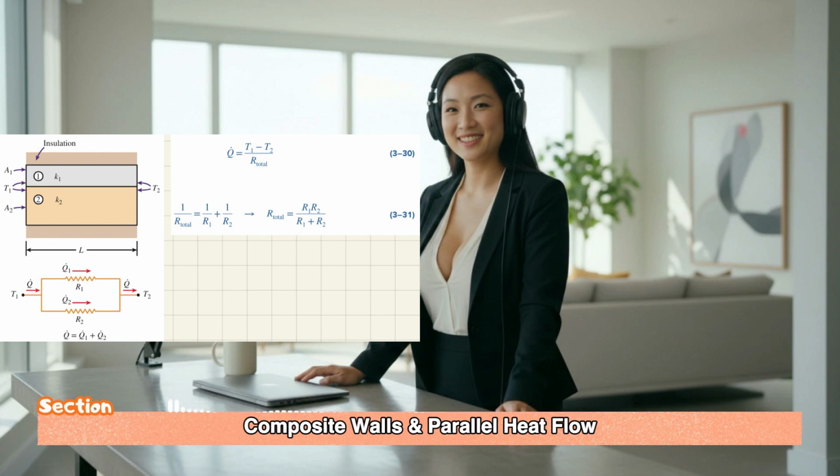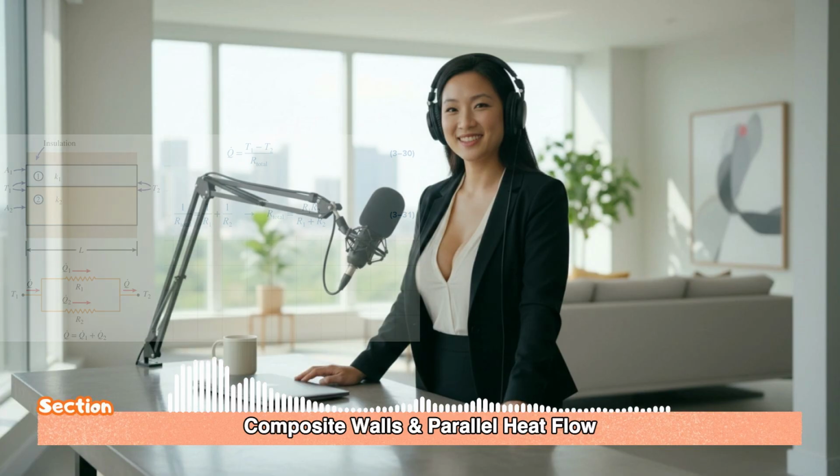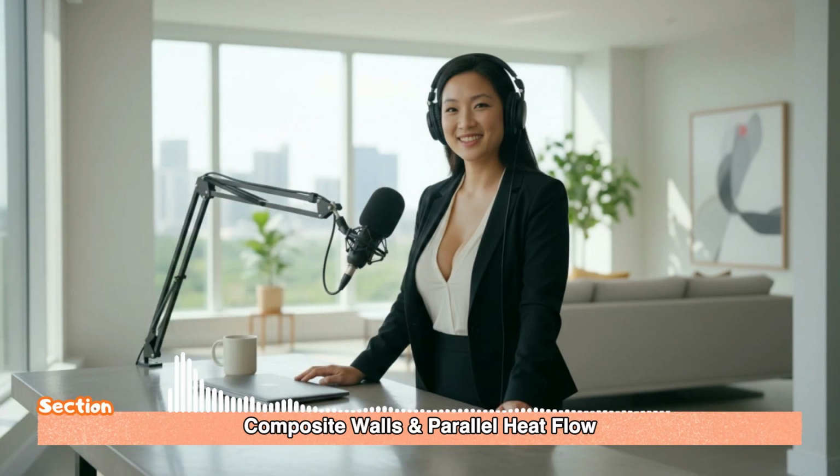It is. The total heat flow is the sum of the heat flow through the stud and the heat flow through the insulation. And because the driving temperature difference is the same for both, the equivalent resistance is calculated using that reciprocal rule: 1 over R total equals 1 over R1 plus 1 over R2. In a parallel system, heat always takes the path of least resistance. So if the wood stud has much lower resistance than the foam insulation, the vast majority of the heat will bypass the insulation and flow right through the stud.